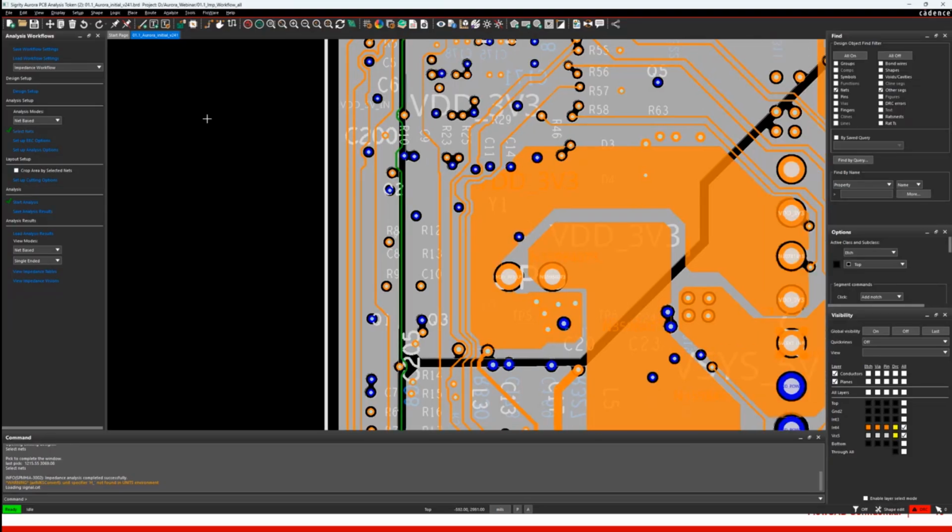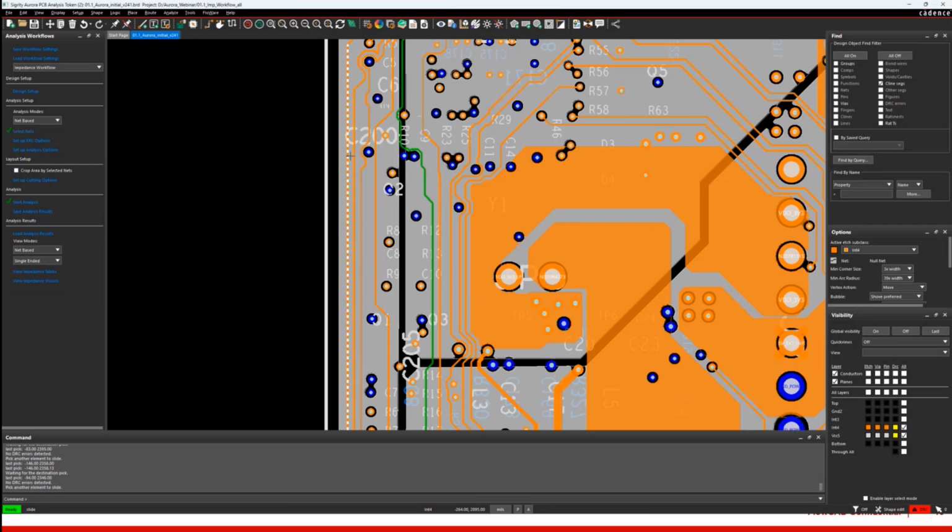Now it's the task of the PCB designer: you find these signals, and you can easily move the traces away to a solid ground plane or a solid reference plane, and then you can directly rerun your simulation to see how that would behave.